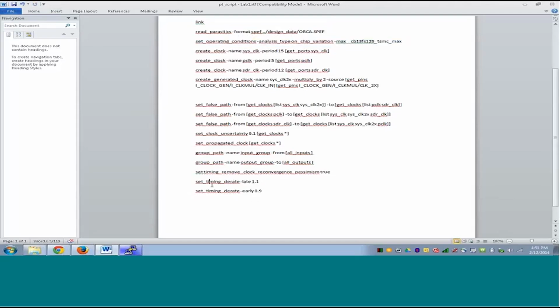By applying timing derates and setting the operating condition analysis mode to OCV, you are making sure that you are accounting for the on-chip variation for the physical effect. CRPR, you are making sure that unnecessary pessimism does not harm your paths. In the clock uncertainty, you have to adjust, you don't have to now estimate the clock skew. Clock skew would be real, calculated, so you need to reduce this value.